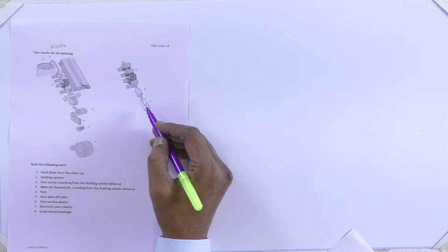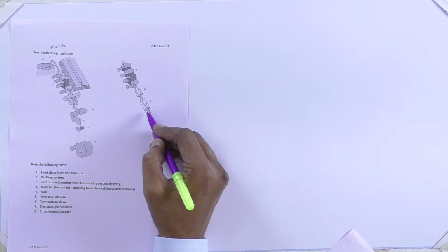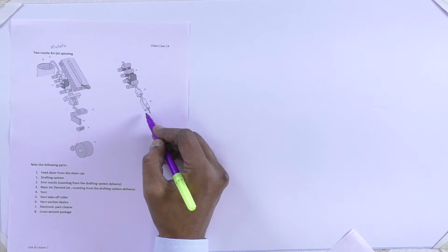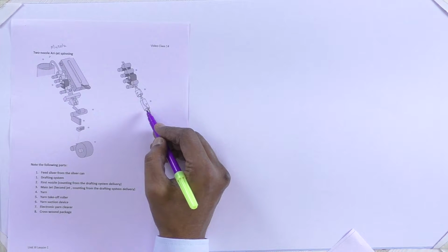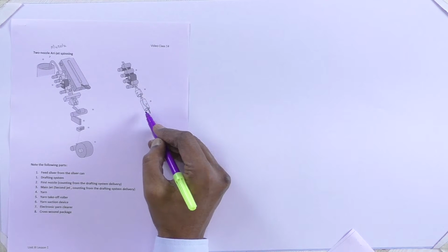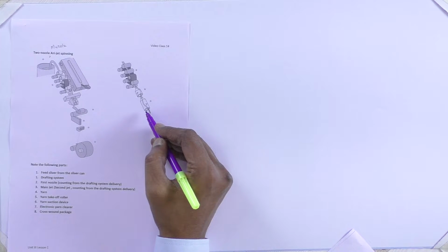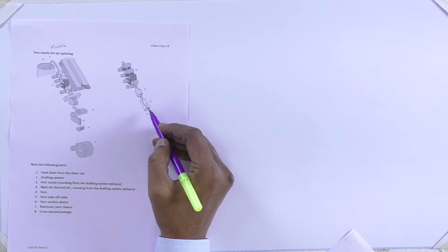The strand achieves a speed of 250,000. Though it is 2 million, because of the nature of the vortex and the air, the real twist achieved, the real rotation on the yarn, is of the order of 250,000 revolutions per minute. The compressed air reaches the speed of sound when entering the central canal of the false twisting element. This is the false twisting element. When the air enters, its speed is of the order of the velocity of sound.